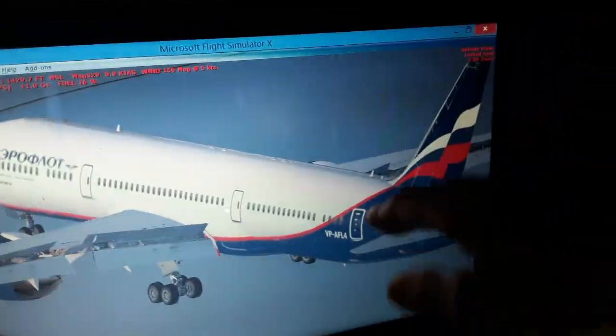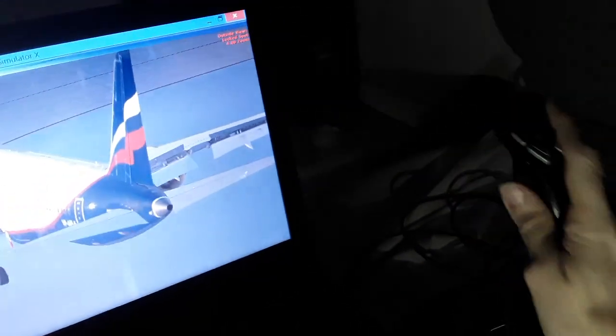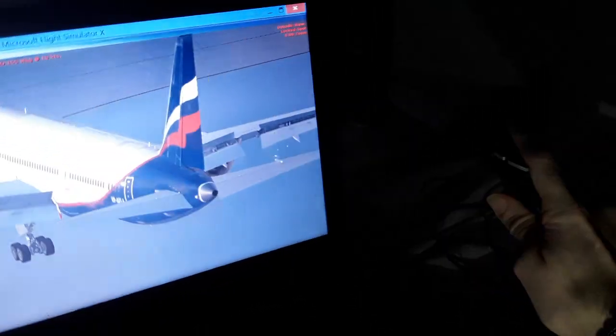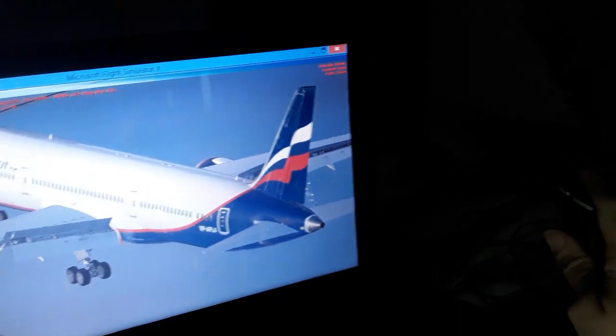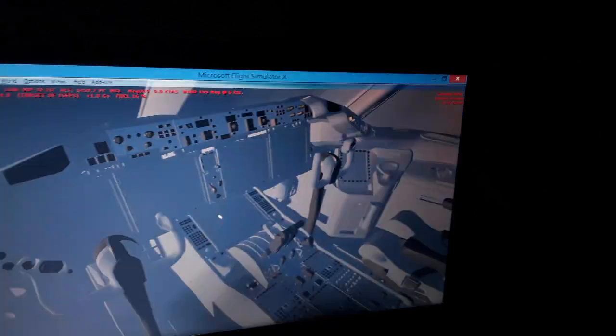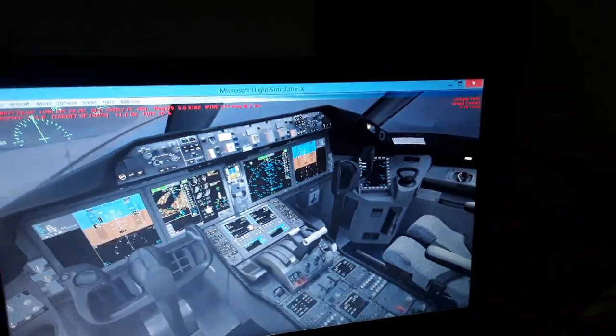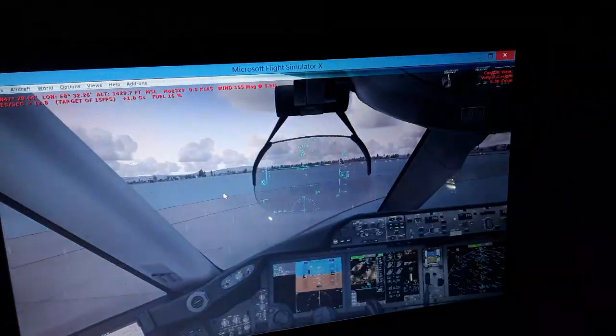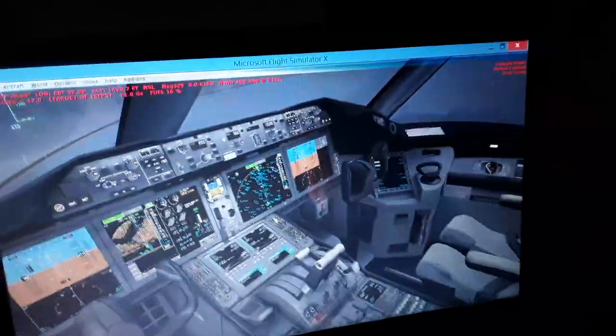You see the horizontal tail moving up and down. The elevator also. So trimming gives a better effect in flight. You can leave the aircraft with hands off as you fly. You have enough thrust and altitude, that is good enough with the pitch trim set correctly.